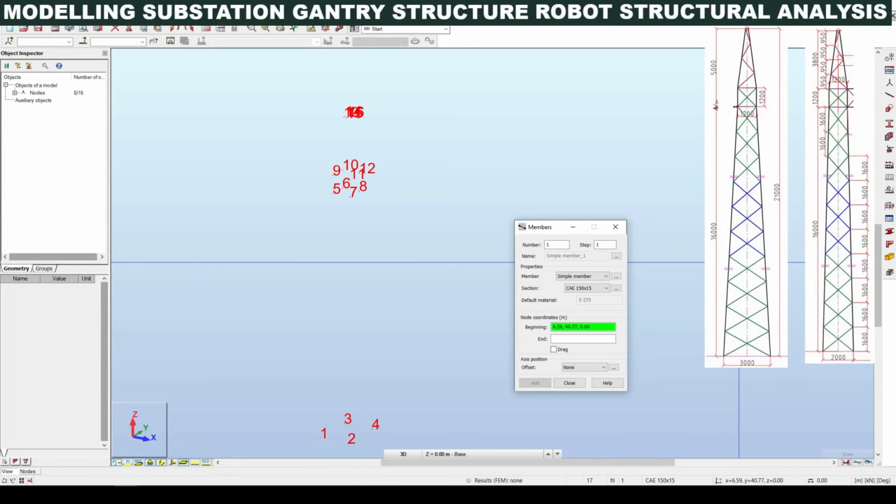Even some of the suppliers used to have up to 12 meter. So in that case we can go for up to 12 meter. So for the critical position, we are considering here as a maximum length of the angle member which are available in market as 6 meter. So we are making the splice which is less than 6 meter here.